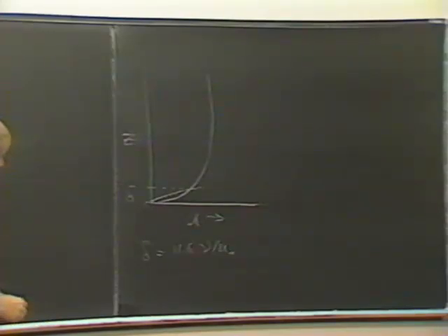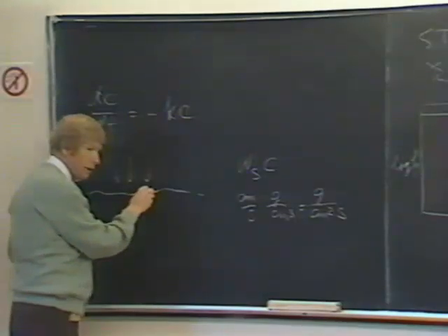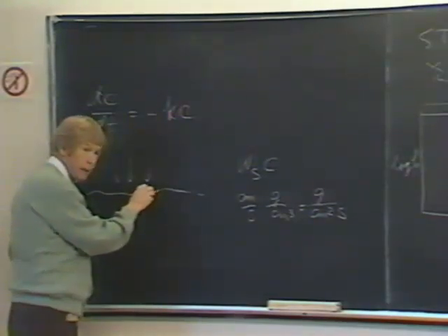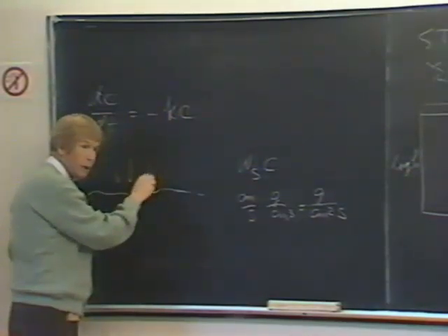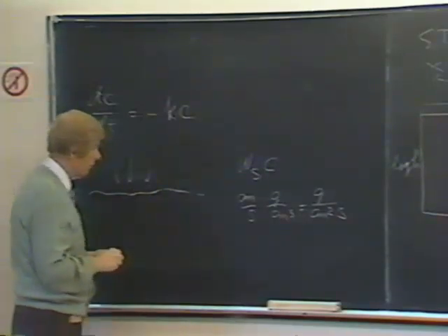Well, in our case here, we have a flux of particles coming down to the bed, but if that viscous layer is collapsing, then some of the particles that go to the bed will be taken back off again. So we need to account for that removal.